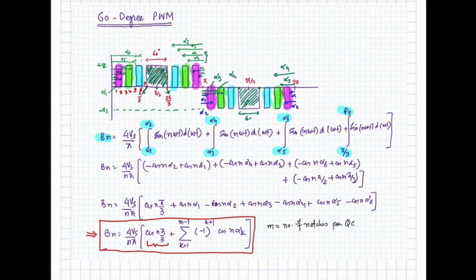by controlling the harmonics at the output of your inverter circuit. So this is one of the PWM techniques and it is very efficient when you are using simple low computational power microcontrollers, because you can pre-calculate all of these angles and you can program your microcontroller timers to generate gate pulses for your switches at the specific time, right.